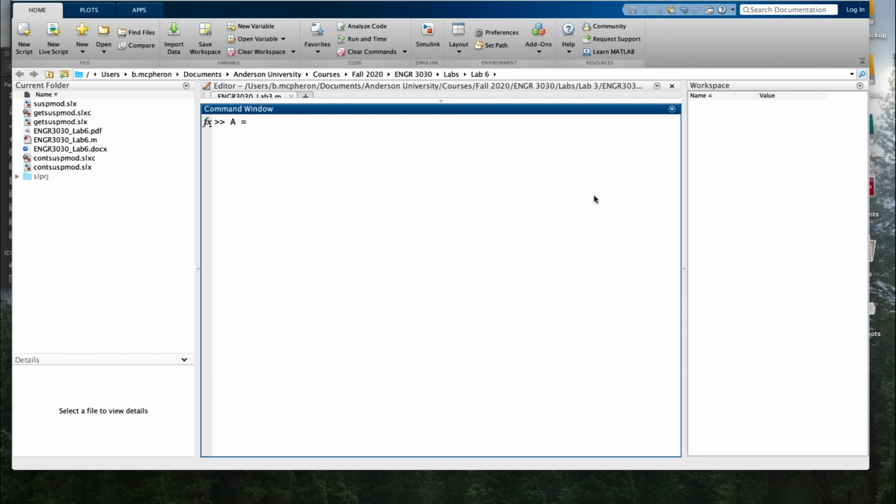Okay, so what I would like to do is test those two examples here. So let's make A equal to 0, 1, -2, -6, and have B be equal to 0, 1. Then I need to construct the controllability matrix. I just want to check that what I have is correct.